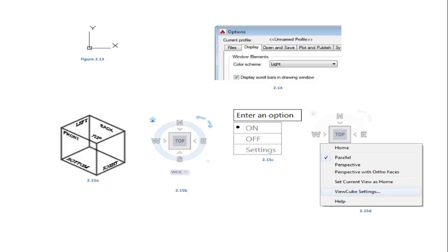And we're going to get into the actual world coordinate system. If you look on page 28 of your textbook, it talks about world coordinate system. If you're putting a drawing together using world coordinate systems, you're using XY coordinates that all start from 0, 0 in this axis point. If this is 0, 0 and I want to start a point up here, I need to tell it to go to X coordinate something and then Y coordinate to start that point. And then from that point I need to know where the next point is from 0, 0. A little more difficult to use.